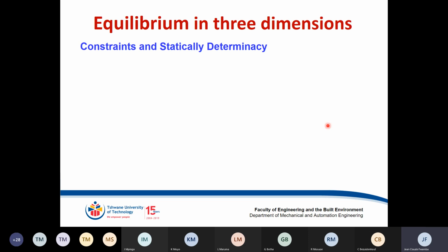By right way, I mean, can you have your system being statically determinate? Statically determinate means you have a minimum number of restrictions, but more effective, preventing any motion in each one of the axes, right? So now let's take the first case where we've got a block and they've put quite a number of restrictions there. Let's now test whether they really work or not.